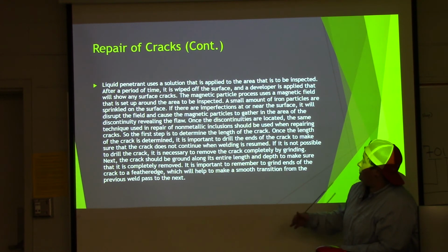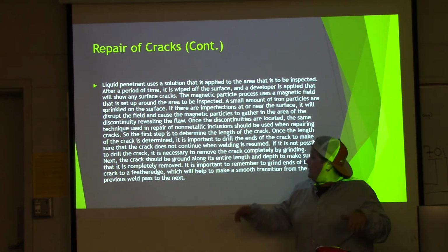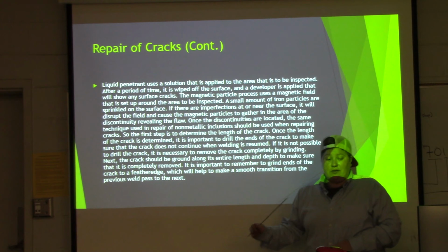It is important to remember to grind the ends of the crack to a feathered edge. We went over what feathered edge means. It means just grinding it down to where it's paper thin, which will help to make a smooth transition from the previous weld pass to the next.